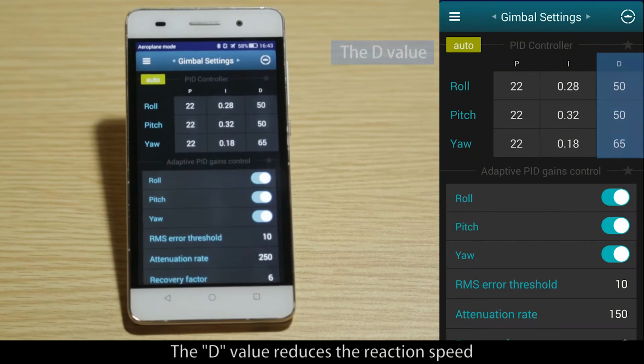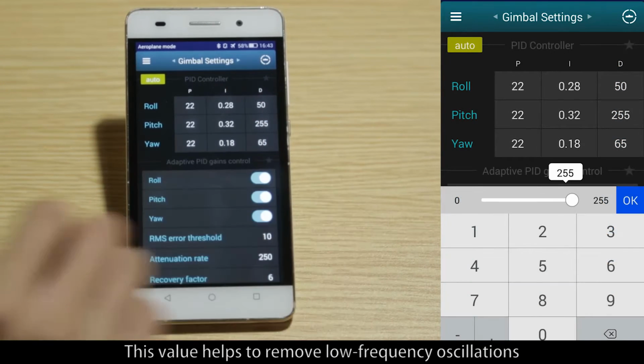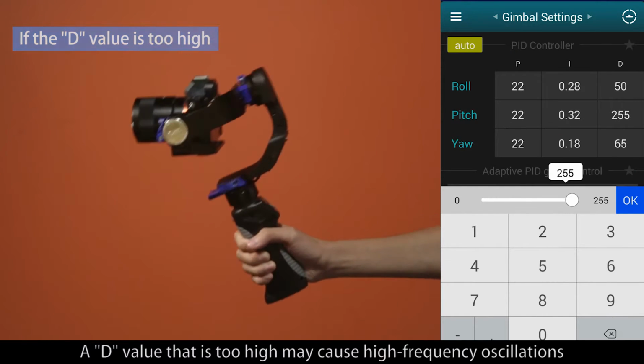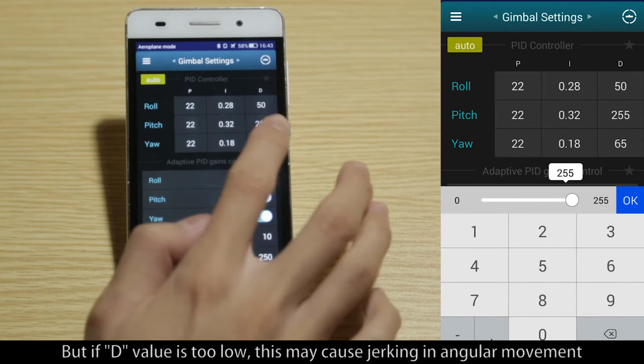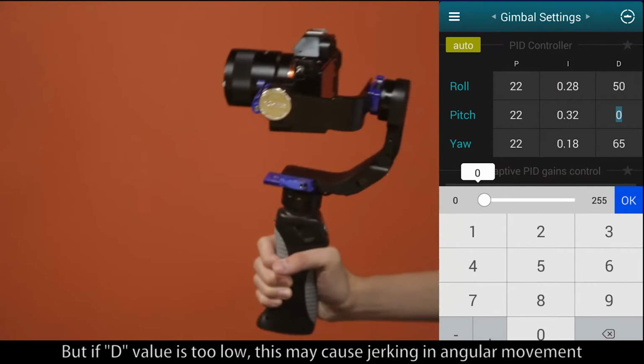The D value reduces the reaction speed. This value helps to remove low-frequency oscillations. A D value that is too high may cause high-frequency oscillations and cause the gimbal to hum. But if D value is too low, this may cause jerking in angular movement.